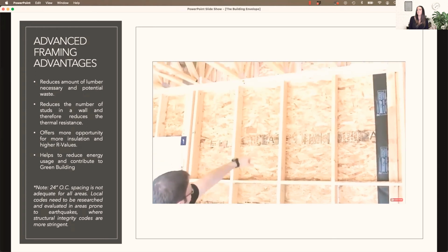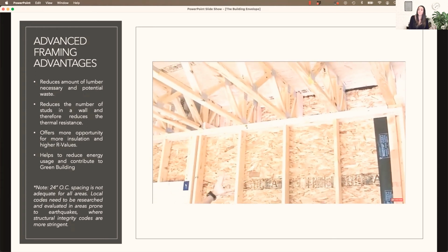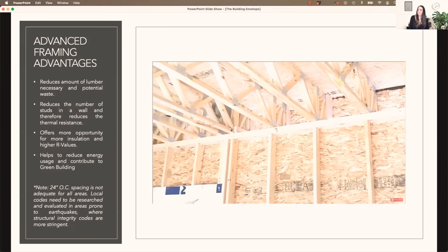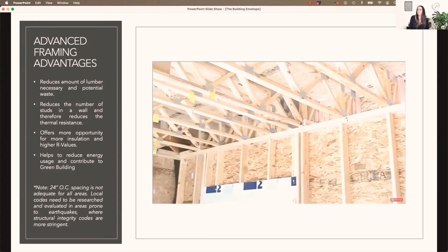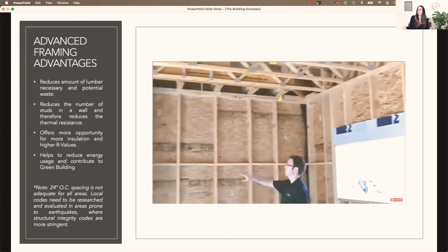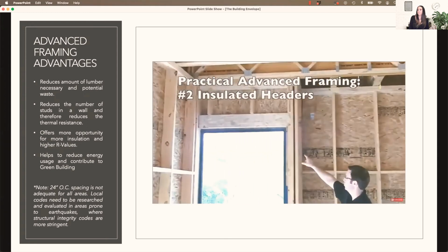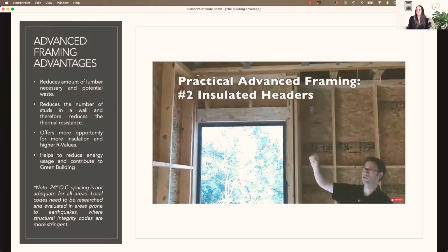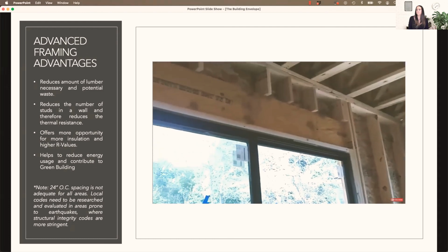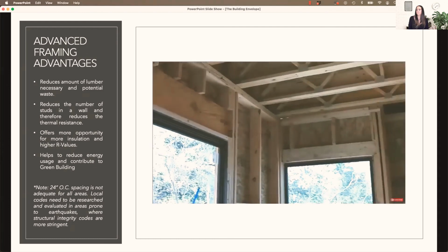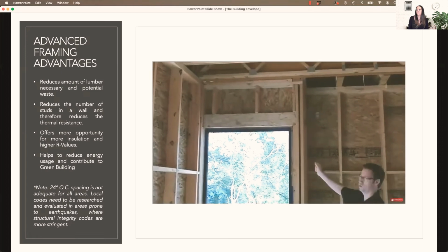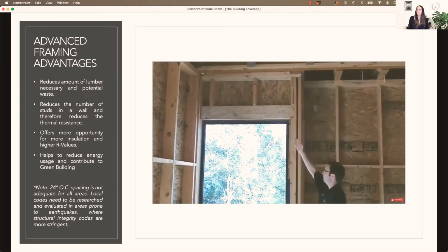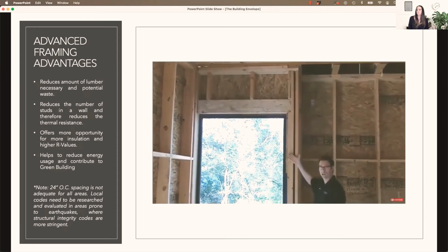You can see how our floor joists up there, these are 2x4 trusses that we've used for floor joists, they've landed on a stud nicely. And then our headers, actually, let's pan over here and show you one of the headers. Our headers are mainly timber strand engineered headers. I'm a big fan of these. We do have a few LVL headers in some other places, but when we frame with a 2x6 exterior cavity, that header fits in basically a 2x4 space. And so it leaves us 2 inches from that outside face of the header until we hit our sheetrock.